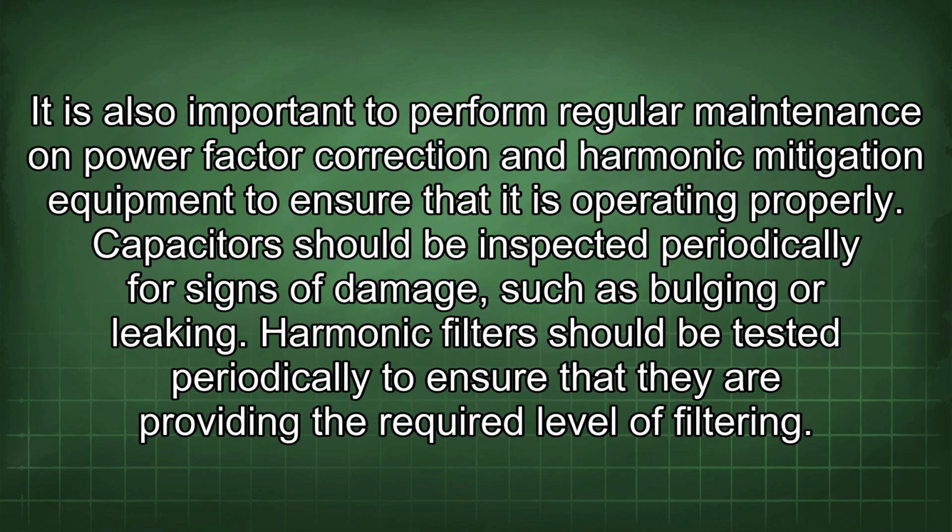It is also important to perform regular maintenance on power factor correction and harmonic mitigation equipment to ensure that it is operating properly. Capacitors should be inspected periodically for signs of damage, such as bulging or leaking. Harmonic filters should be tested periodically to ensure that they are providing the required level of filtering.